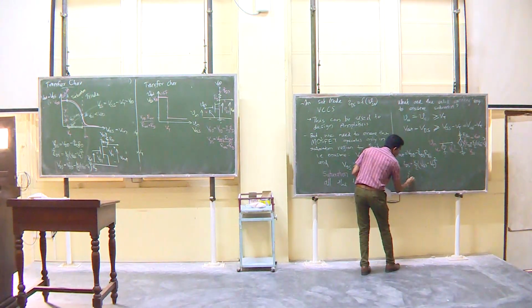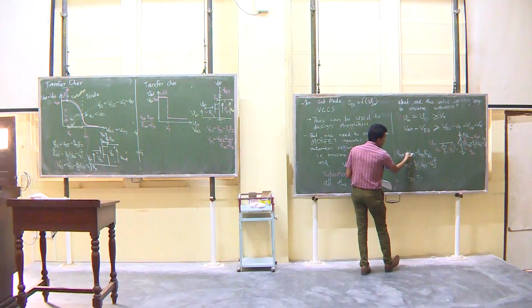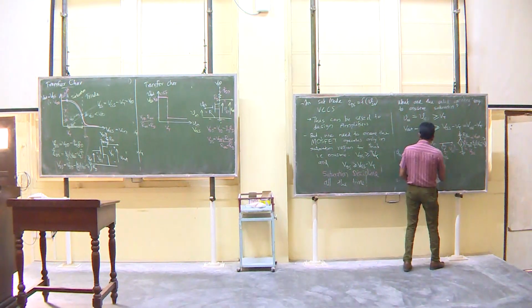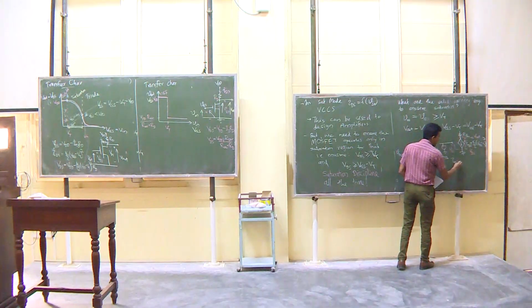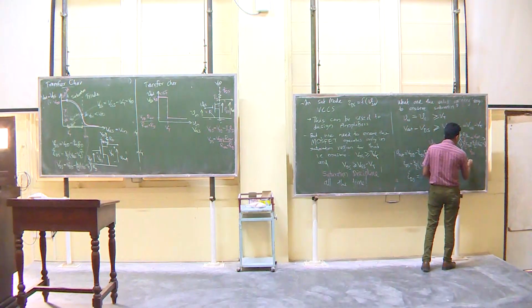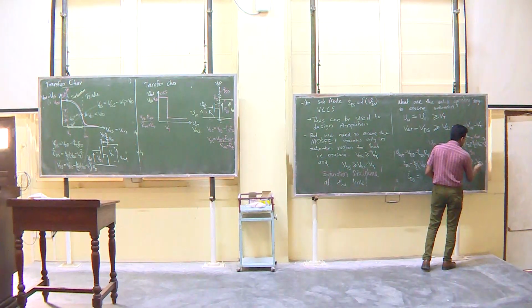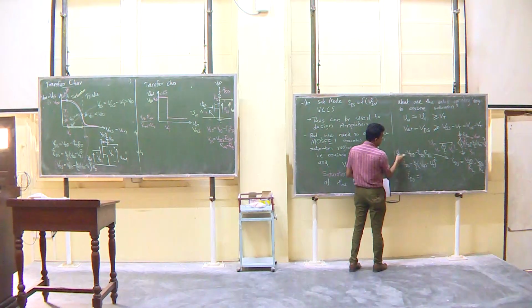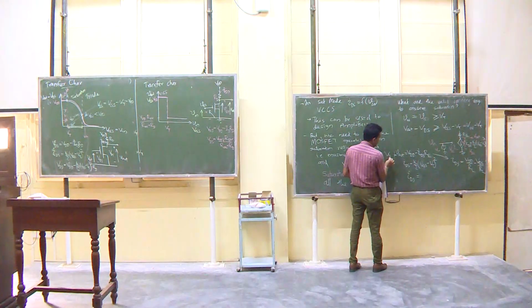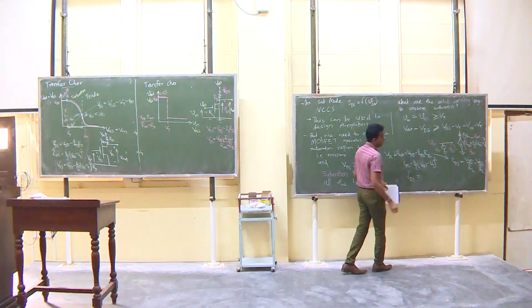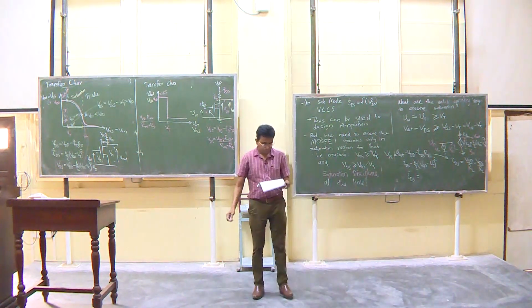So, IDS. From this equation, I can write IDS as equal to VDD divided by RL minus VDS, this is the output voltage, divided by RL. So V out is equal to VDS. Using this, I am dividing everything by RL and taking ID this side. If I write it like that,